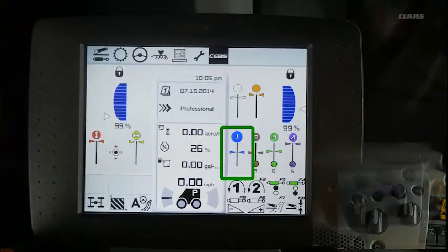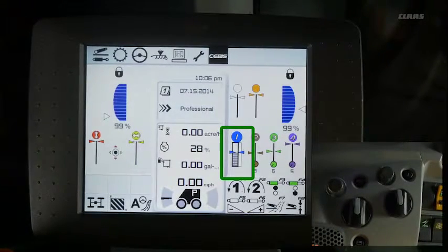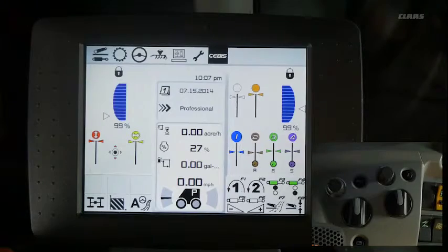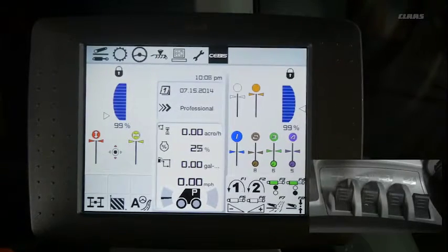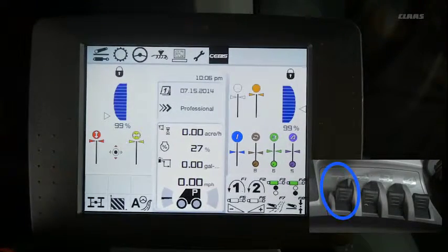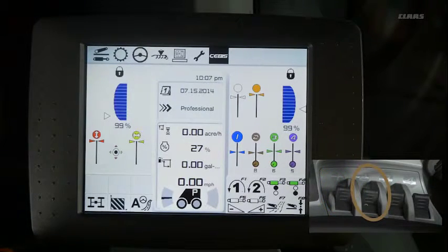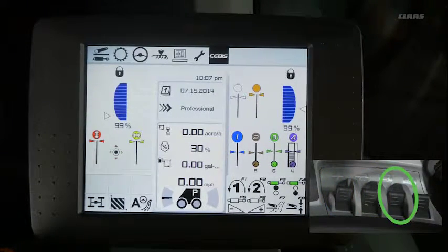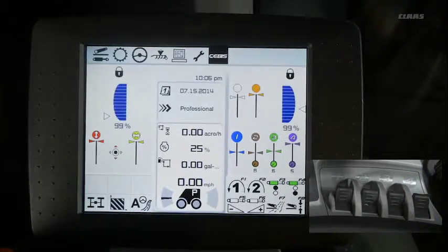Now if we operate the blue valve with the paddle controller and let go of it, the valve will immediately shut off. If the blue valve is pulled to the detent position, it stays on indefinitely, providing a constant flow. It will stay on as long as the blue valve is on demand. Valves 1, 2, 3, and 4, or in this example, the blue, brown, green, and purple hydraulic circuits, are all controlled by the paddle controllers instead of the function buttons. As the purple valve is engaged, notice the remote immediately reaches the desired flow rate.